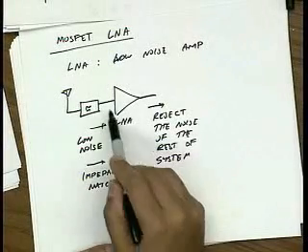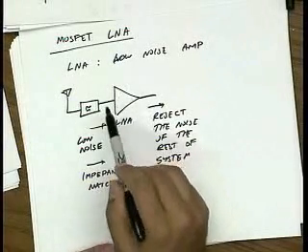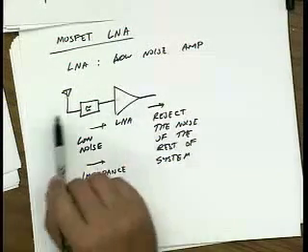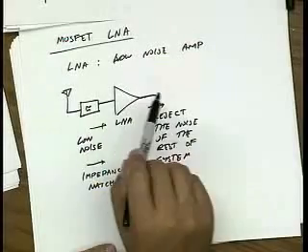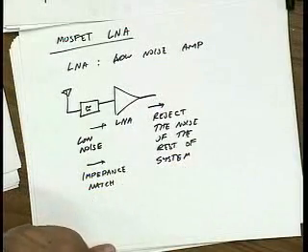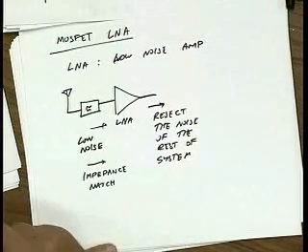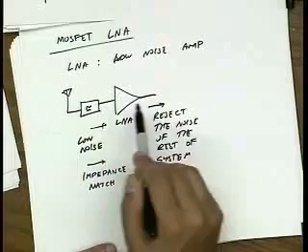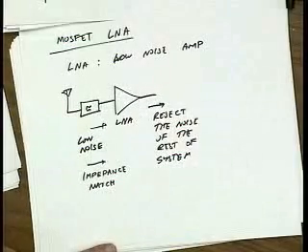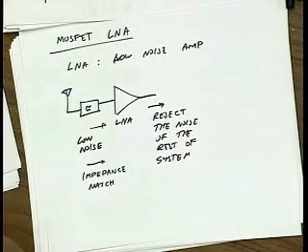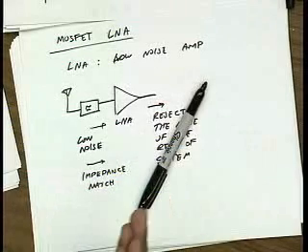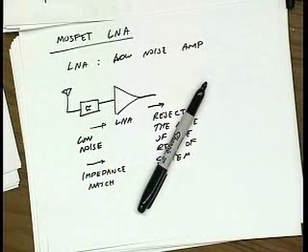On the other hand, if this is not matched to the characteristic impedance of the transmission line, then the input impedance is kind of unknown, because it depends on, one, the length of that transmission line and its characteristic impedance, and two, it varies as a function of frequency. So then the amount of power that I transfer depends on frequency, it depends on how you lay out your board, everything gets complicated. So what people do is they don't want to have to tell their customer, well, you have to put down the LNA and then you have to have 1 inch of transmission line with this characteristic impedance, and if you have a bend in the transmission line, put an extra capacitor here.